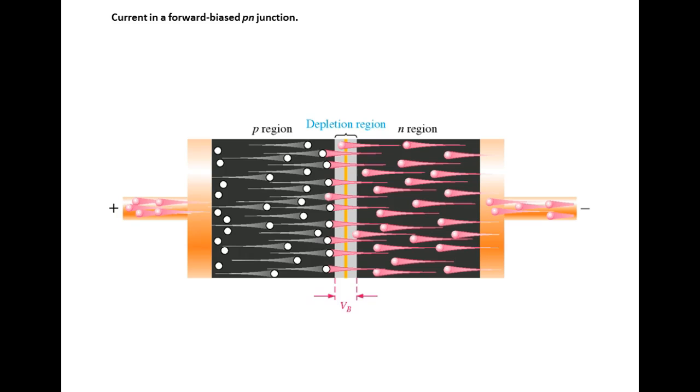And these guys, what determines the physical size? The physical size of the diode is determined by how much current flows through it. I mean, it is a current valve, right? You understand that? It's a check valve. What determines the size of a check valve in fluid power is how much flow you want to go through. So we have these diodes right here. Let me pass these around. These are two. And y'all should be able to see the cathode.